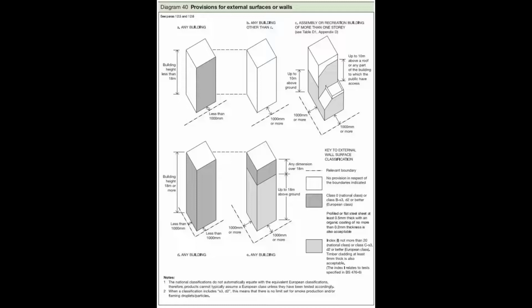And where there are scenarios because of existing constraints, for instance, an existing building that might be listed, some building regulations have to be questioned, and other factors need to be considered to deal with that. It might be a management situation that resolves that particular regulation. Simply because on a Grade 1 listed building, one might not be able to implement the most up-to-date building regulation. That could be to do with conservation, historicism, or simply the pure functioning capability of the construction of that building.